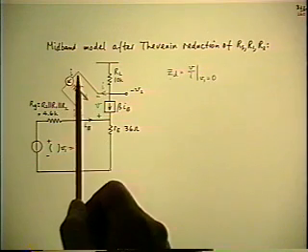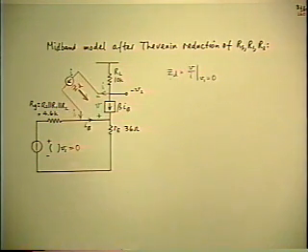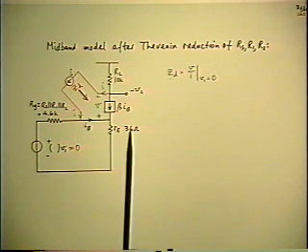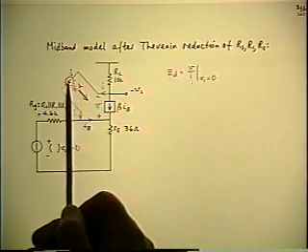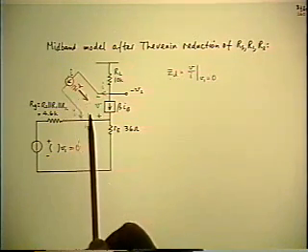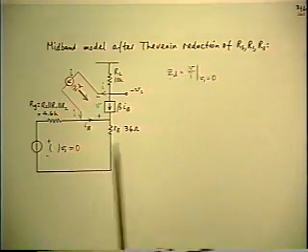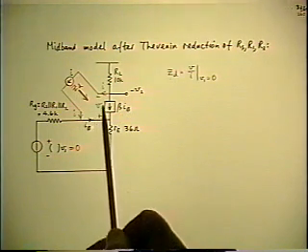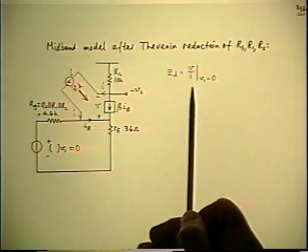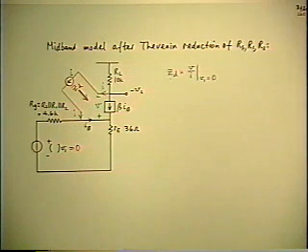I've drawn the independent source as an ideal current generator because, once again, it can be anything you like. Why not make it the easiest thing to do the calculation? Since the denominator is the independent input, I chose an independent current source to provide the test signal. So all I have to do is do as little analysis as possible in order to find V as a function of I. Then I can divide the I into it, and what's left behind is the answer I want.